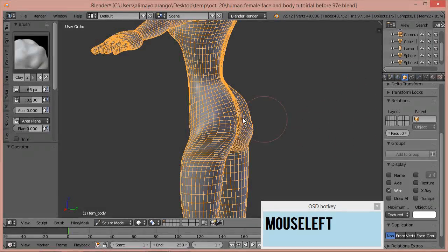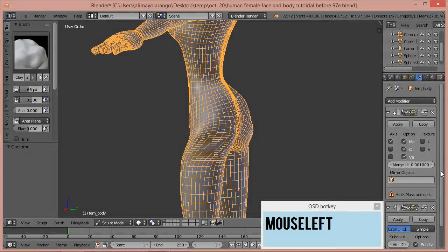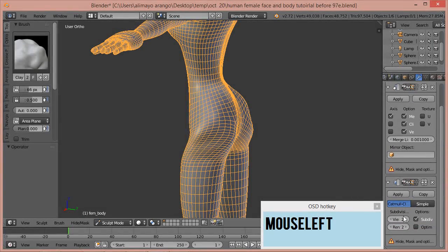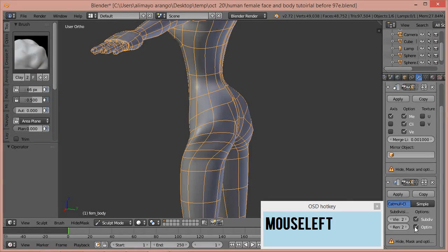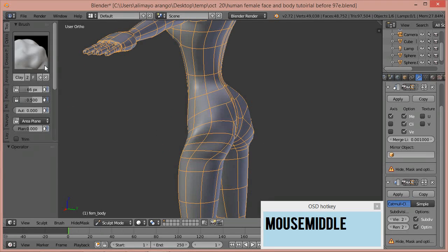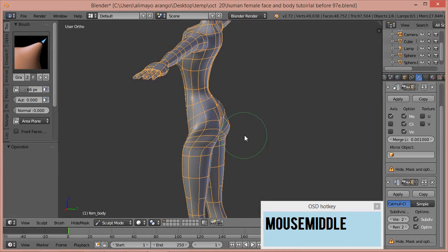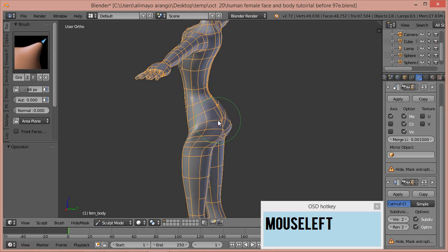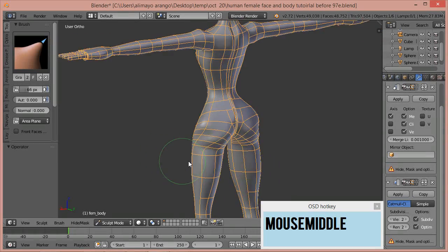Okay, we don't want to have too many lines to distract us, because basically these lines are showing where we can manipulate things. What you do is click back on this modifier button, look for your subdivision surface, and right here is your optimal display button. Put a check mark right here, and now you can see where you actually can click. It still doesn't give me what I want, so I'm going to go here to grab, and you can actually just grab and then smooth down.